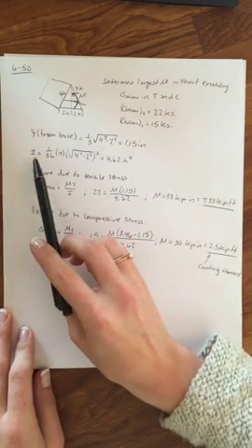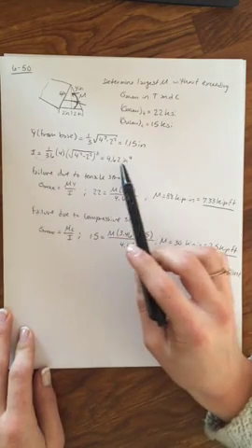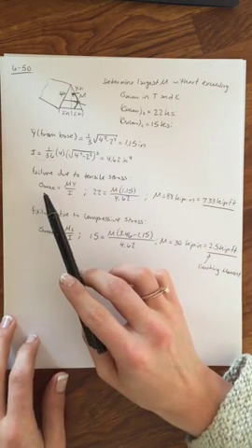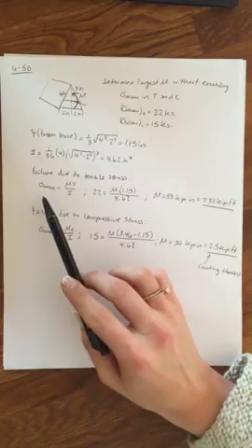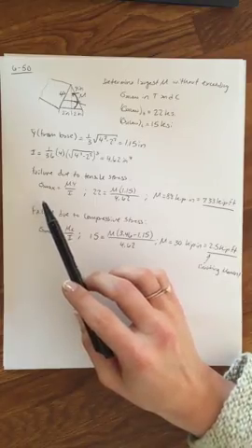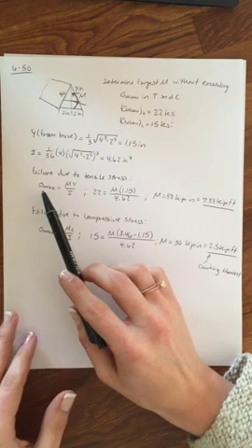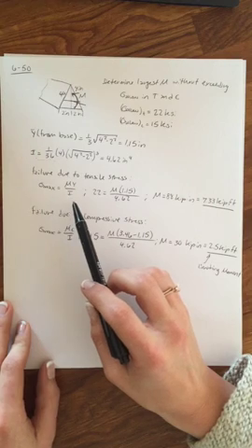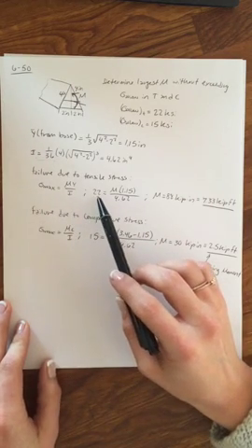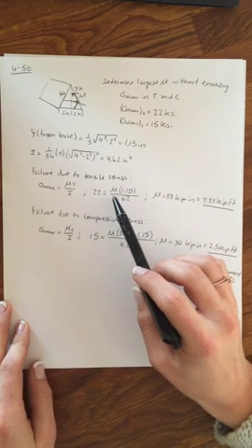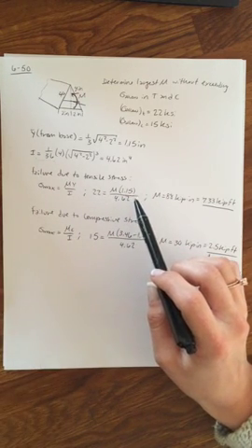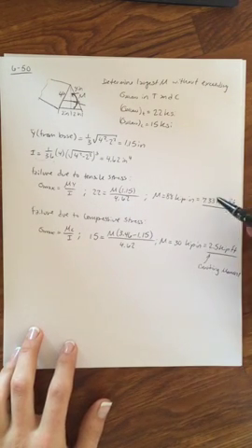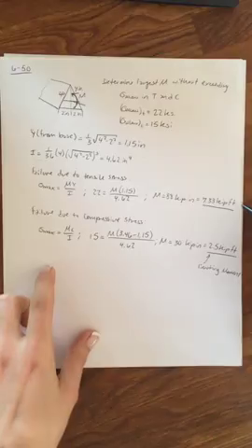And then we can go ahead and find the polar moment of inertia, which we find is 4.6 inches to the fourth. And now we're going to think about what is the failure situation due to tensile stress. So the maximum stress from the flexure equation we just found, the moment times y over I, is given to us. 22 equals the moment we're trying to find times y, which we've already found, over the polar moment of inertia. We plug that in, and we have 7.33 kip feet.